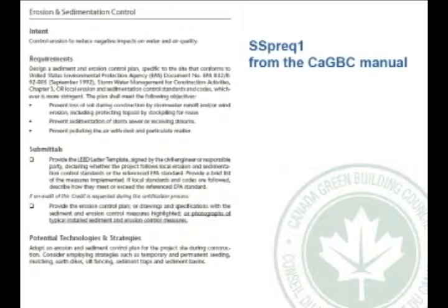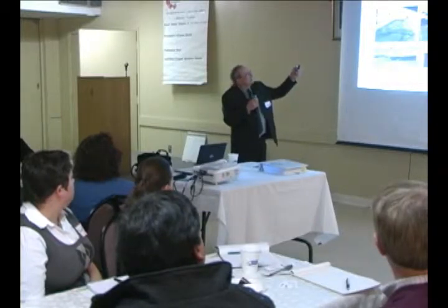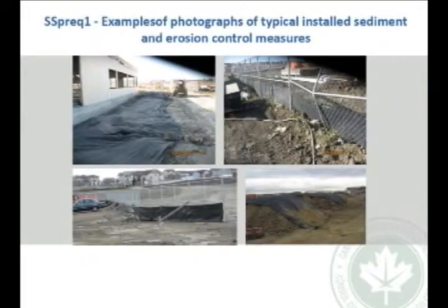First off, as I said, LEED has to identify very clearly what the submittals are. The designers and specification writers, when they're looking at going for the points, need to look very closely at these and make sure that they get documented in the specifications. The way to do that is when the points are first identified, that this is what they're going to go for in the project. This is a sample of an erosion and sediment control plan. Photographs. You need to take photographs at 3 different stages during the project showing the actual installation.